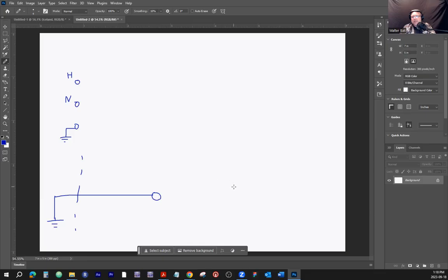Now we might have a second terminal here that has a wire connected to, let's say it's a grounding strip, all copper, for example, and there's another screw terminal, and this thing is connected to here. Technically, yes, because this is all connected. This is a copper bar, and these are just different screw terminals, so you can add on to this. So it's all connected. Yes, this terminal is also technically grounded because it's sitting at the same potential as ground.